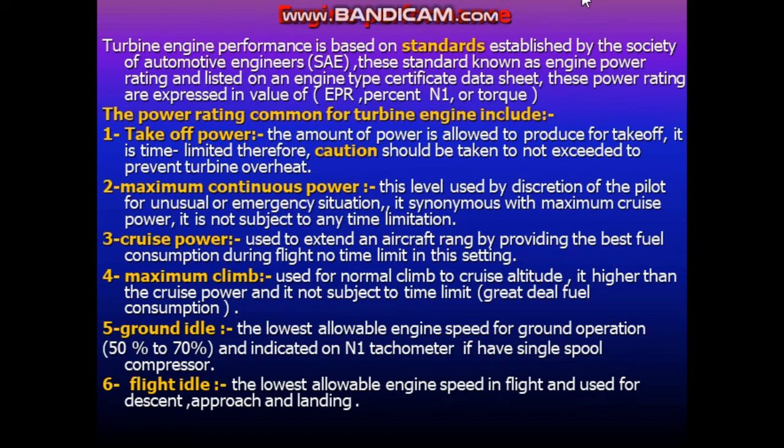Engine performance. Turbine engine performance is based on standards established by the Society of Automotive Engineers. This standard is known as engine power rating, and is listed on an engine type certificate data sheet. These power ratings are expressed in values of EPR, percent of N1, and also the torque.